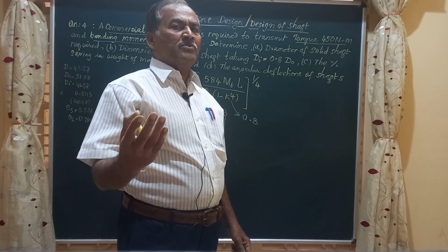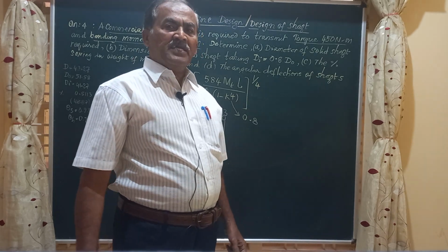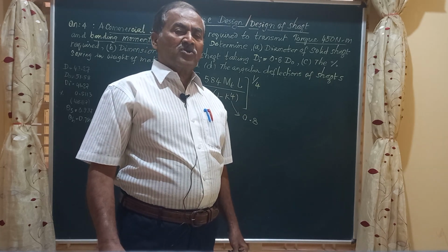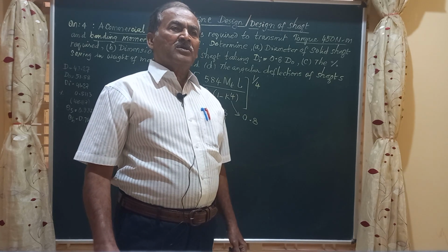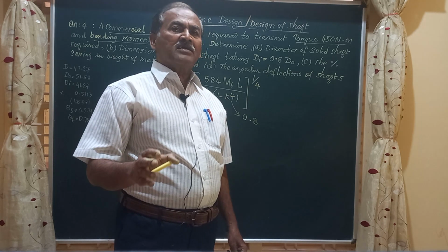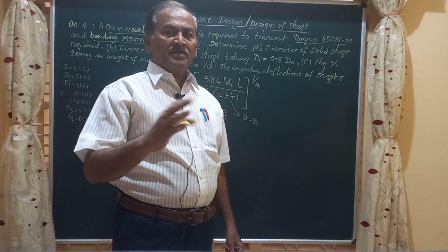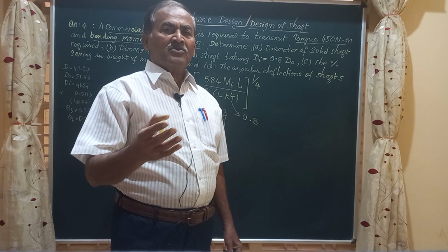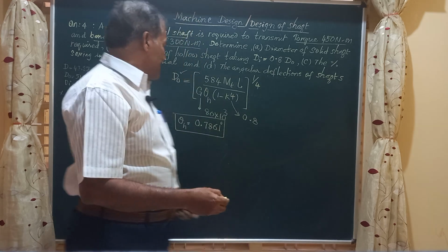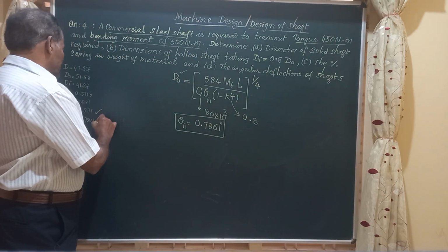So you may remember or recall that while studying strength of materials, you have proved that a hollow shaft is stronger and stiffer than a solid shaft for the same value of torque to be transmitted. So you can say that the answer you have got is right.